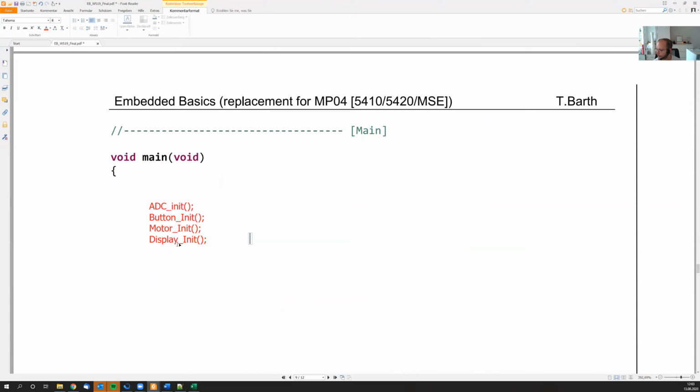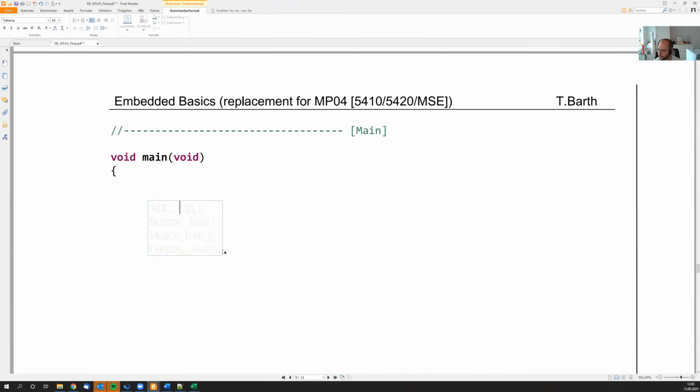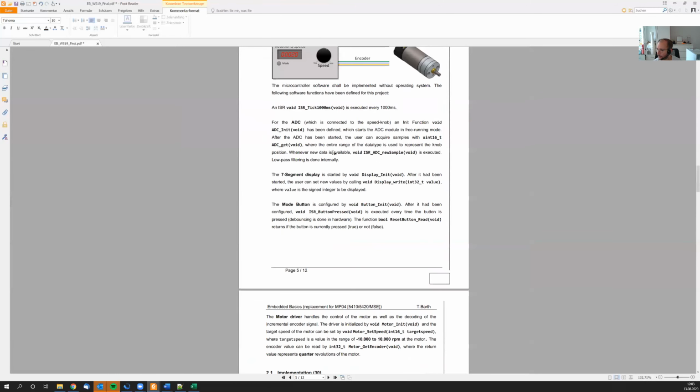So here, what we use in LED is like start LED. Instead of that, we are using the init function. We use start ADC, and here we are using ADC init. Yeah, because this is the function as it was specified in here. This start and stuff is something PSOC related, but if you work on other microcontrollers, those functions might have different names.